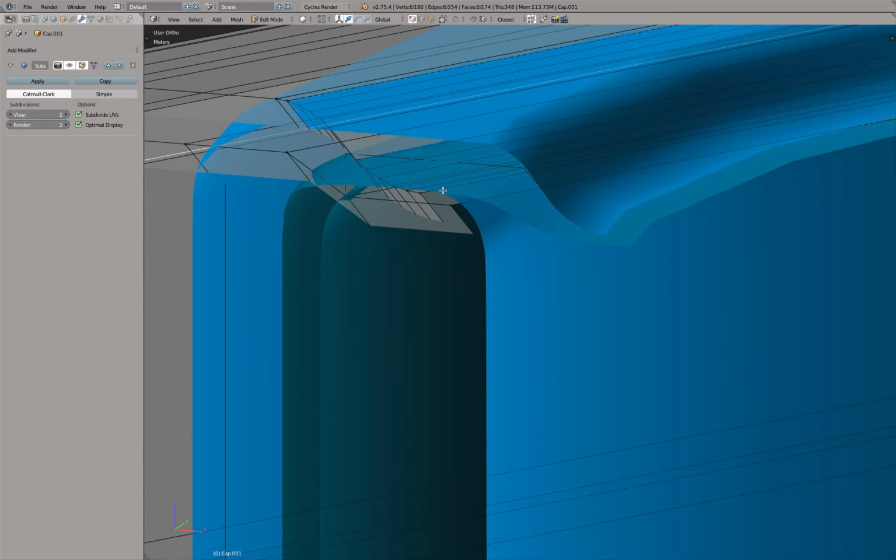So for example here we can select this edge, and then again loop select, and I would like to fill in a space, kind of like make a loft. And the command for loft with polygons very often is called bridge.